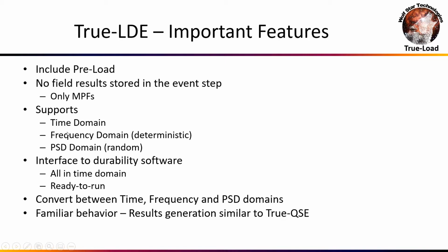Oftentimes your durability tools have very specialized cases that make these things work, but they don't work in the generalized cases. So when we push it to the time domain, we're able to make it work for any solution, okay? And we give you ready-to-run decks for your durability software. And what's really great is that we can convert your results between time, frequency, and PSD domains. So you could have done a frequency domain solve and want to look at the time domain, and we can flip a switch and give you those results in the time domain very easily.